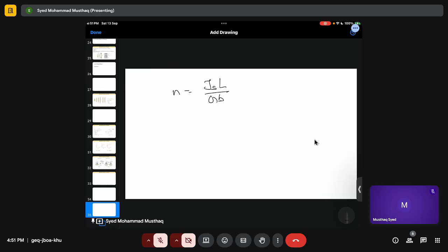Now we know the critical shear stress required to initiate a dislocation source in the adjacent grain, tau c, will be equal to n times tau s, because you already have tau s. So you have L tau s squared upon Gb. Now what is my tau s? Tau s will be equal to the square root of Gb tau c upon L, the whole to the power half, and tau s is the applied stress minus tau i.